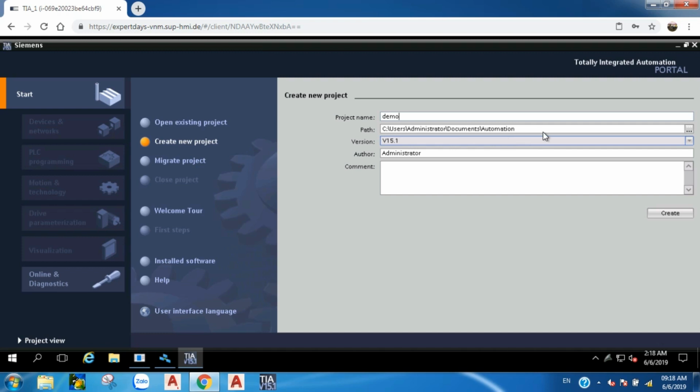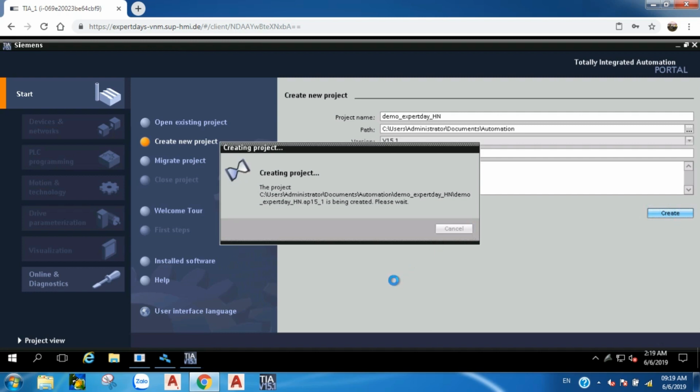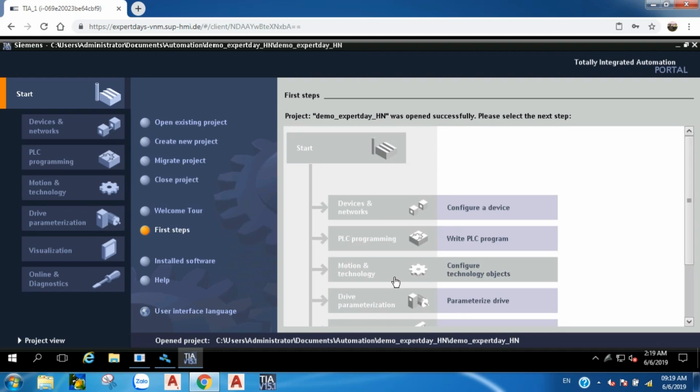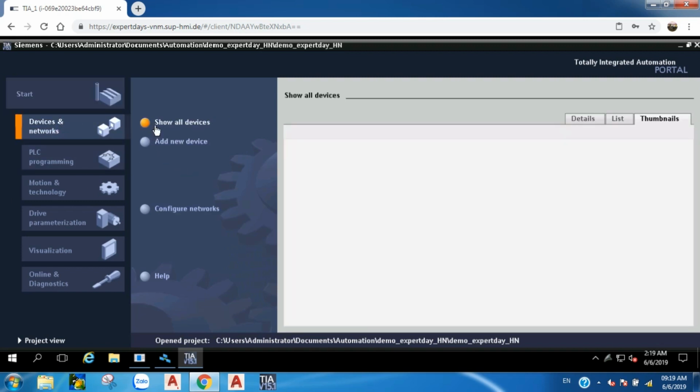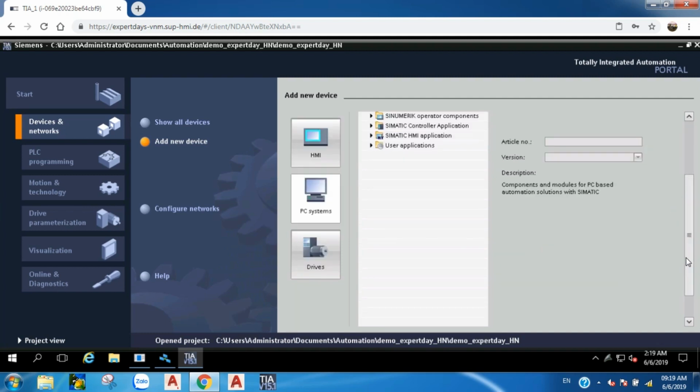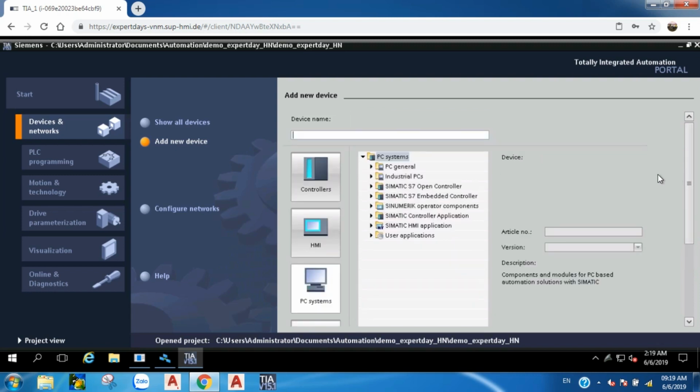On the bottom, you see the 1515R and the 1517H. When you introduce the device in your WinCC project, you see the whole H system, which includes two PLCs. You can also see that under the S7-1500 there are two systems, PLC1 and PLC2. No deep redundancy know-how is required, so you just configure it like a simple 1500 PLC. And you can scale the switching time.